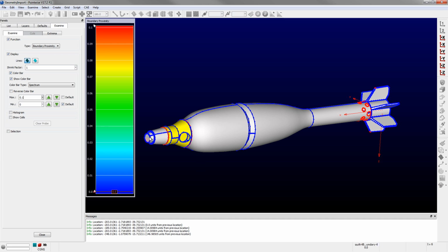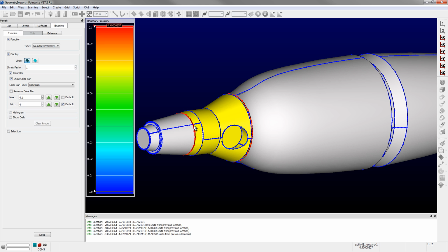that we saw before. If we zoom in here, if you look right up here and right down here, and I hover over that, you can see that that distance is 0.4. So that gap is 0.4 millimeters. Okay. This gap is 0.1 millimeters. So it's pretty small. We can actually probably just fix that using the model assembly tolerance. This gap is probably large enough that we should use a surface to kind of bridge that, and that's what I'm going to do. I'm going to create a surface to kind of fix that gap.